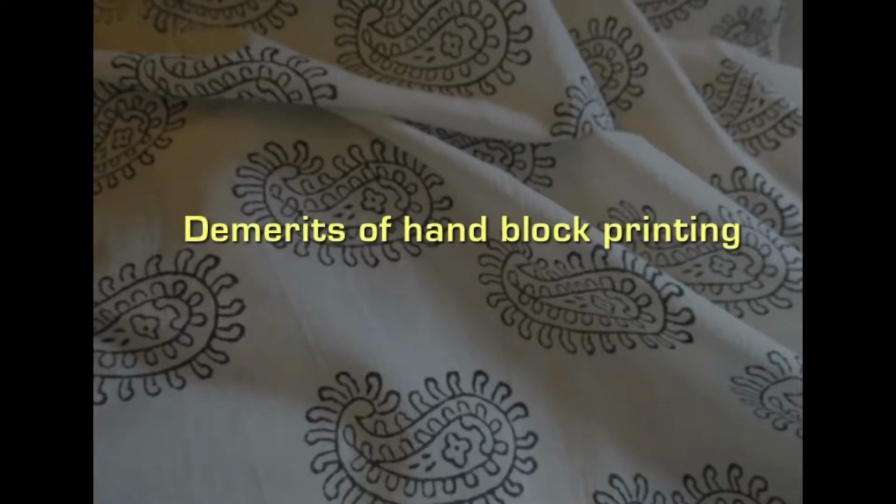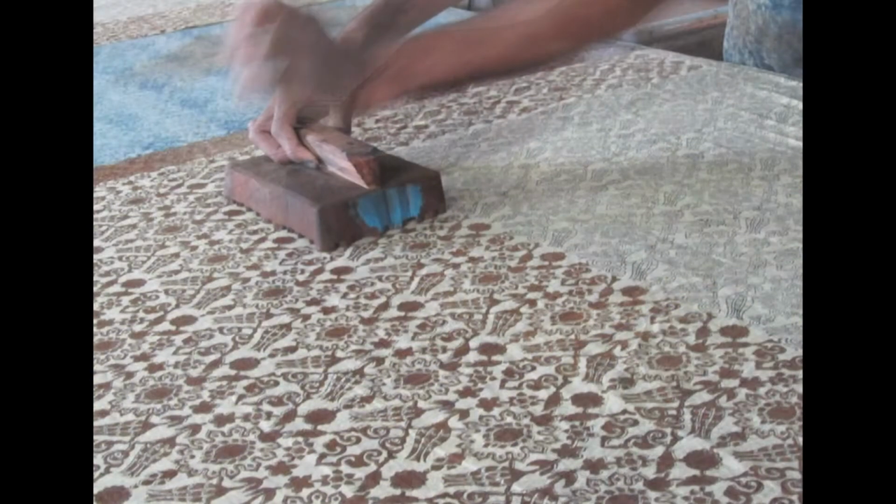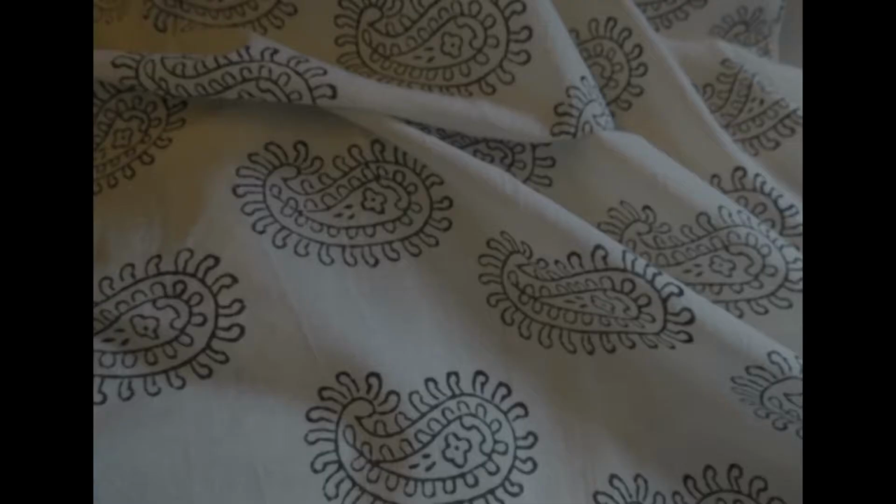Coming to the demerits, this method is slow and involves a large amount of labor work. Printed fabrics cannot be produced inexpensively in large enough quantities by this hand block printing method. Due to the separate impression of the block, it becomes somewhat difficult to join up each impression or repeat perfectly. Very long or wide repeats cannot be printed by using large sized blocks of greater weight.